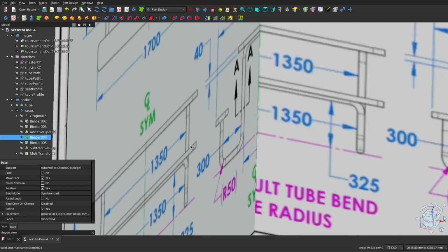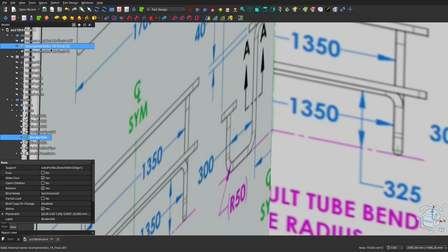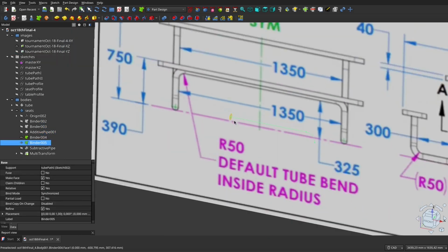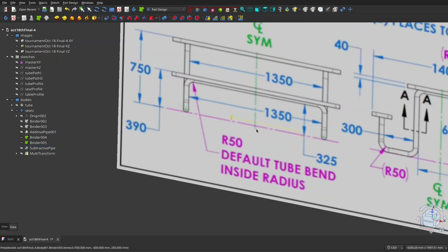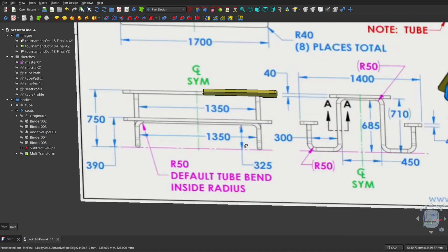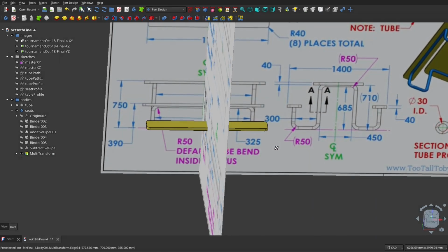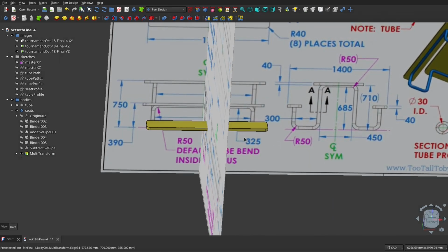For this subtractive sweep, we create a subshape binder using the external cross-section of the tube, and the path corresponds to the first part of its trajectory. Performing the subtractive sweep results in the groove you see here. After that, we apply two mirrors to obtain one complete bench, and then another mirror to complete the second bench.